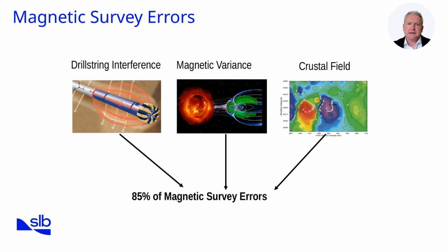The magnetic declination in a given area may change slowly over time, possibly by as little as 2 to 2.5 degrees every 100 years or so, depending on its distance from the magnetic poles. For a location closer to the pole, the declination may change by 1 degree every 3 years. This may be insignificant to most travellers, but it can be important if using magnetic bearings from old charts, metes, directions in old deeds, for locating places with any precision.